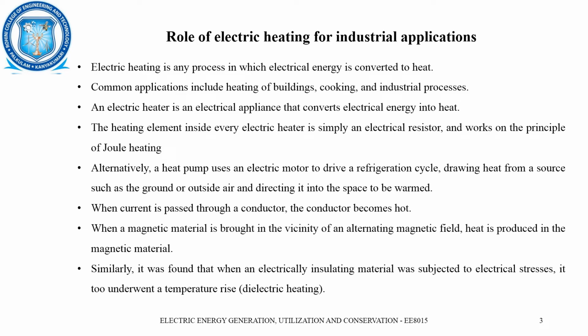An electric heater is an electrical appliance which is used for converting electrical energy into heat energy. Normally, the heating element used in an electric heater is of resistance type. It's a resistance material, and if electricity is passed over that resistance material, obviously it will create heat due to the I square R loss, that's Joule heating.